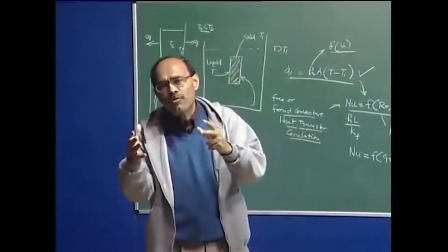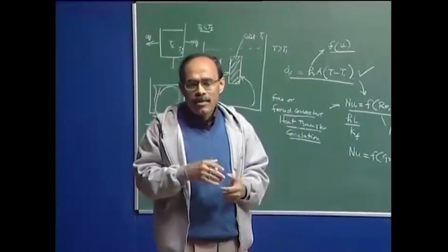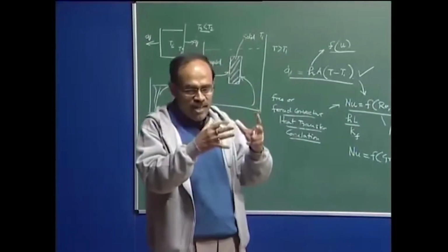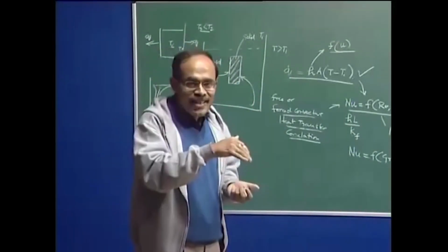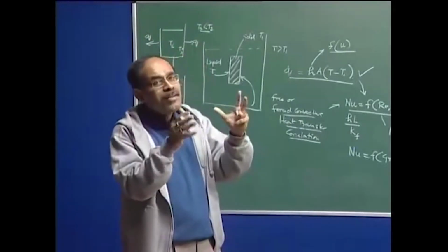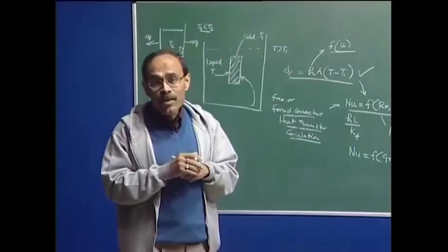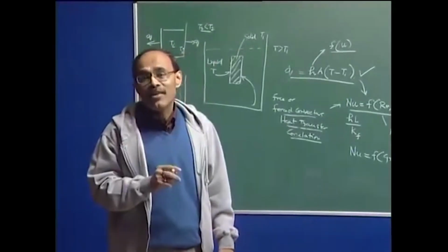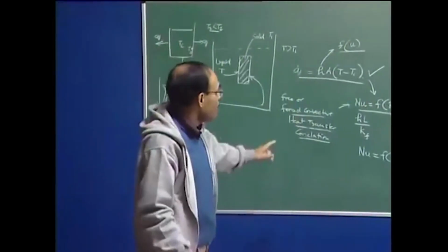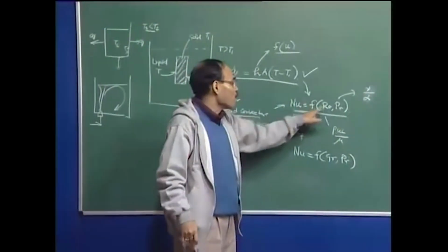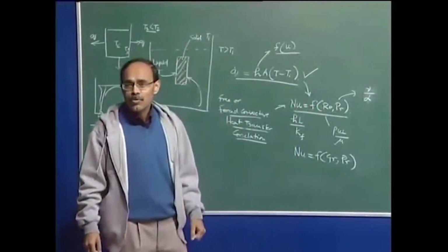You try to understand the process, the flow and the heat transfer well, and then you look at the literature and find out whether a correlation is available for the situation in which you are interested. If you do not find such a correlation available, you have no option but to carry out experiments and find out what the applicable correlation itself is.